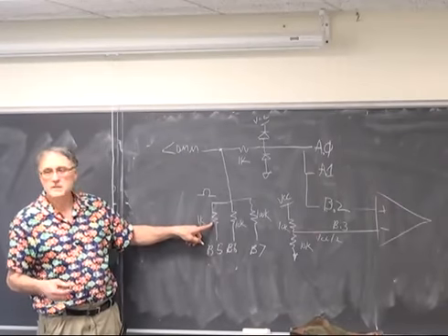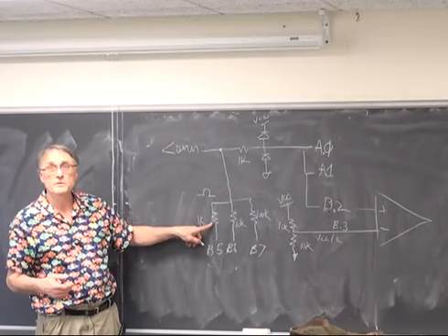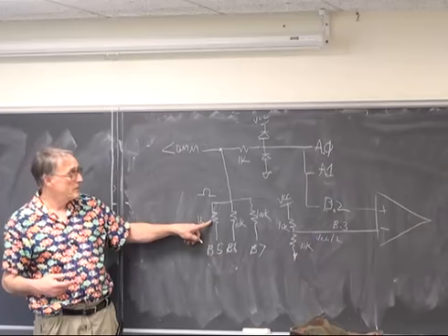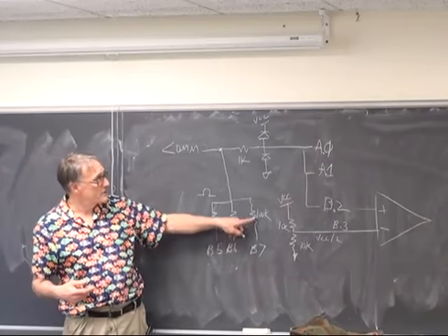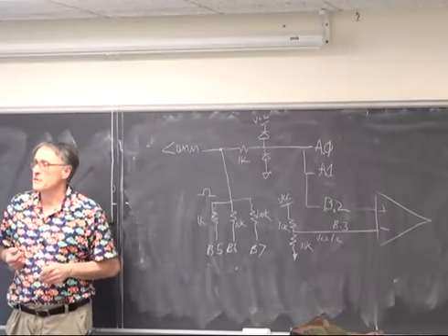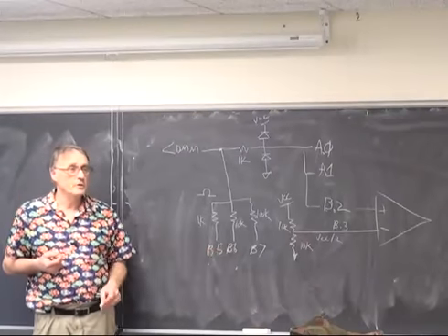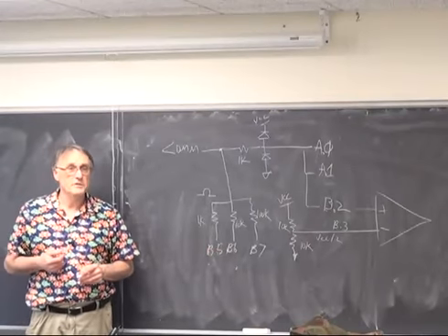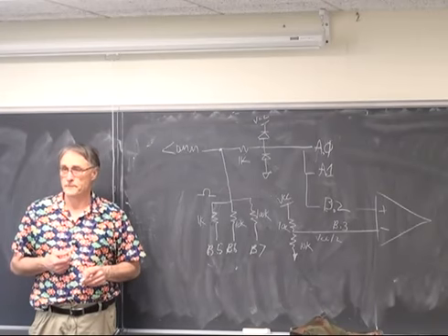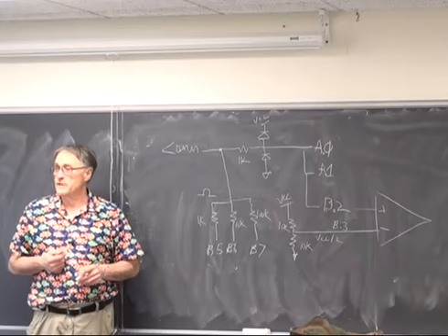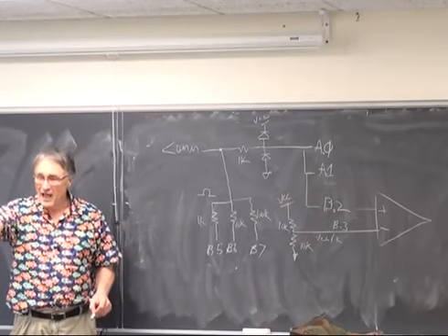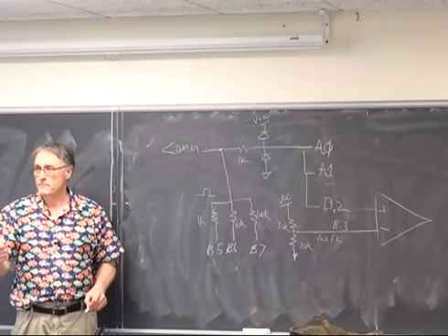So for small resistances, and you have to measure from 100 ohms to 100K, for small resistors you're going to want to use this. You want to turn on B5. For big resistors under test, you want to turn on B7. The way you turn off one of these ports is you make it an input, and therefore it goes to high impedance. It draws no current. It's like turning off the switch. So the outputs here are either going to be output and high or input and low.